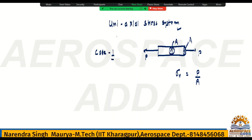But now, we have a uniaxial stress system, but the plane is not normal. This is the normal plane. For the normal plane we have written the stress, and the value is sigma x equal to P by A. All right. But what about when we have a plane which is not normal, which is oblique? Oblique in the sense that the plane is inclined from the horizontal, suppose with angle theta. Then what will be the stress acting on that plane?